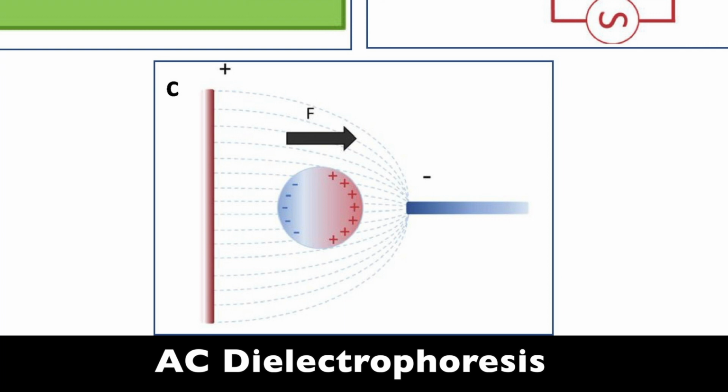The dielectrophoresis force, DEP force, is most effective near the edge of the electrodes, where the strongest electric field gradient is present, and it rapidly decays with distance from the electrode. Also, the dielectrophoresis force is very sensitive to the object dimension. In addition, in biological solutions, the protein manipulation by dielectrophoresis is frequency dependent because the effective polarization of the proteins is determined by the protein structures and their electrical properties.